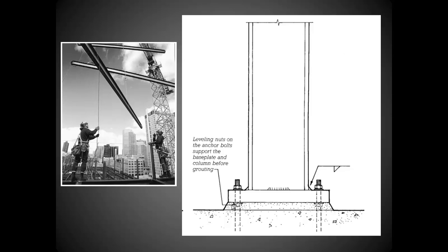leveling stays accurate. Here we see a weld symbol, meaning that we've got a fillet weld on the near side here, so this indicates fillet weld on either side of the flange. You can see the width of it here is not all the way around. If there was a circle here, we would see that it would be welded all the way around, but it's not. It's just in certain segments.